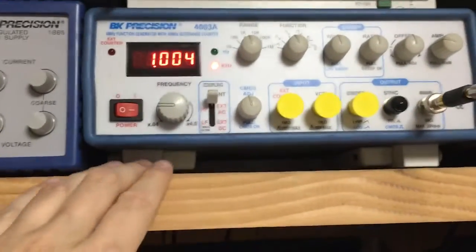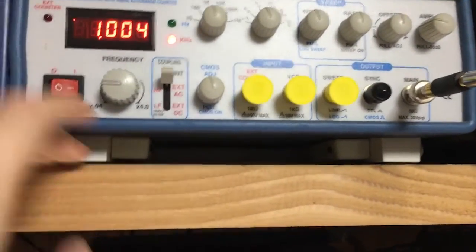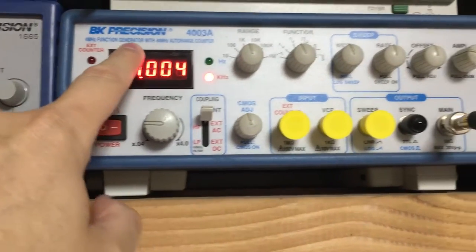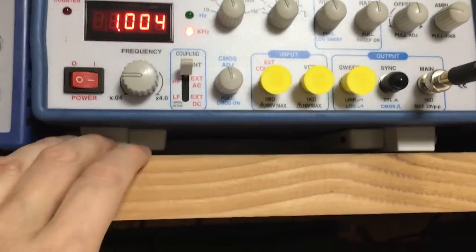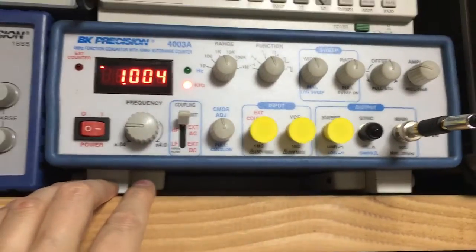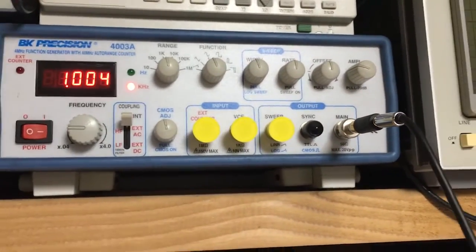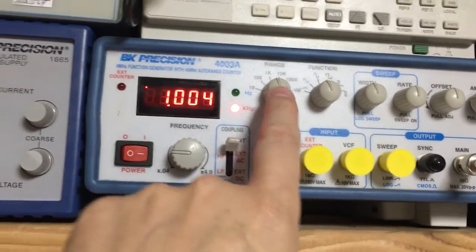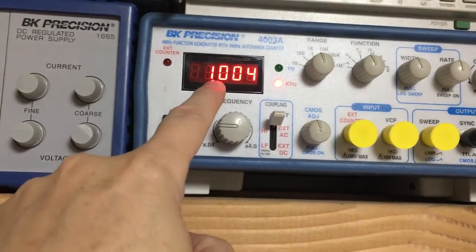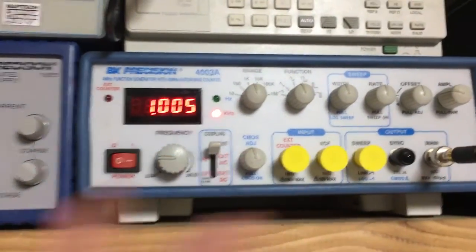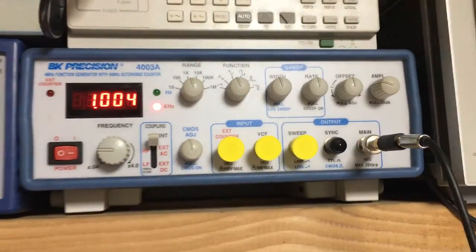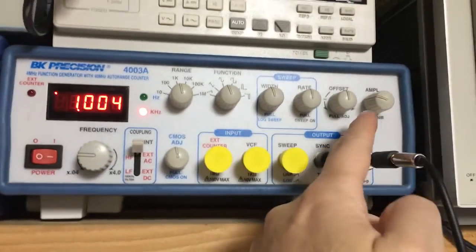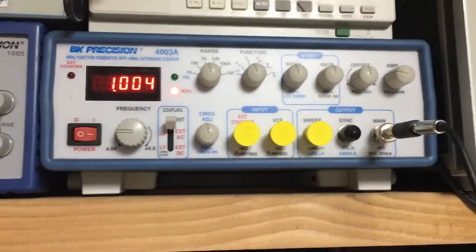So first and foremost, I'm feeding out of the audio oscillator. In this case, it's called a function generator. This thing will go from 0 to 4 megahertz, and we don't need all that. We just need about 0 to 20 kilohertz to do audio stuff. So right now I've got the setting on 1K here, at 1.04, so 1 times 1K. We've got 1 kilohertz, and we've got it set on sine wave up here. 1 kilohertz sine wave, and I can adjust the amplitude of that sine wave with this knob right here.